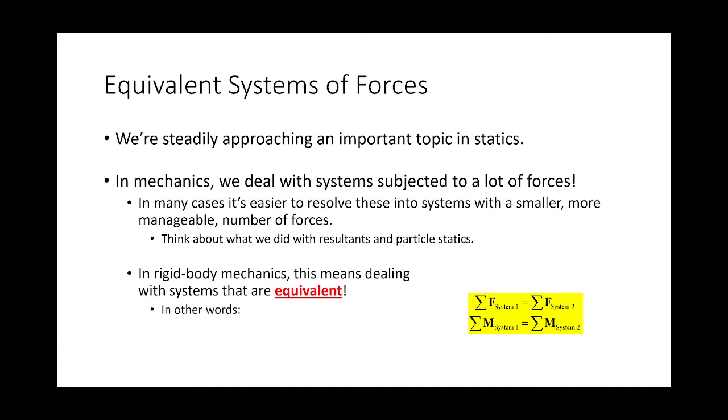So what we'll do is we'll say, I've got a system that has 8, 9, 10, whatever loads on it. Let's simplify it to just a force in the x direction, a force in the y direction, and a moment. Or if it was 3D, Fx, Fy, Fz, and Mx, My, Mz. Just take all those forces and make it a whole lot simpler, okay?